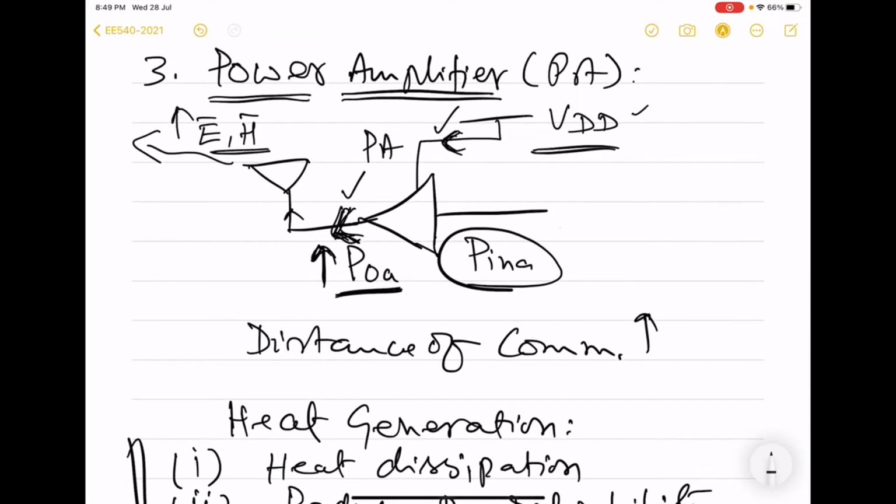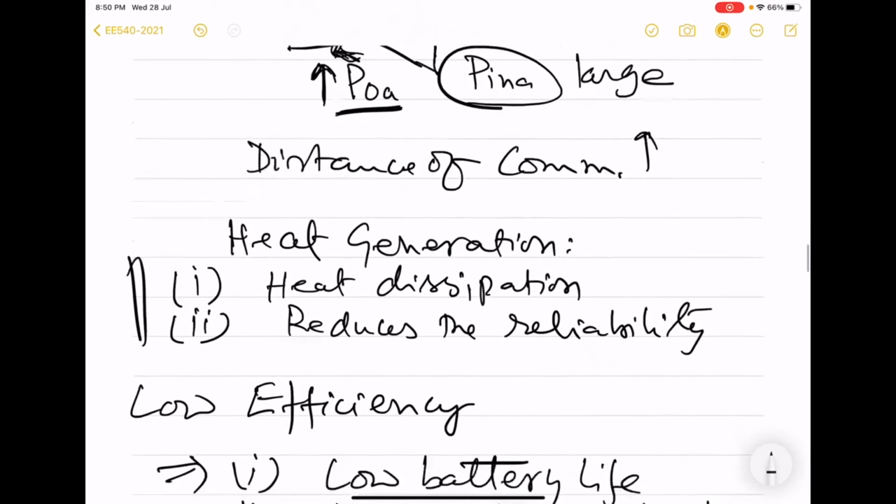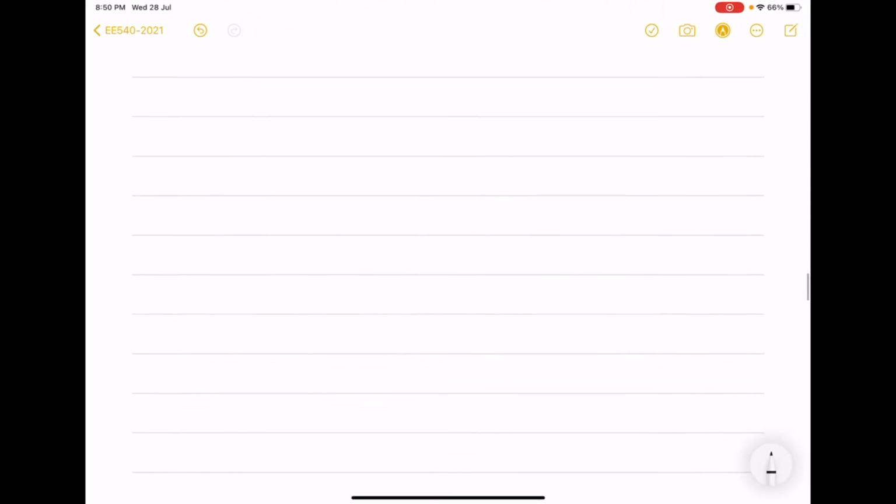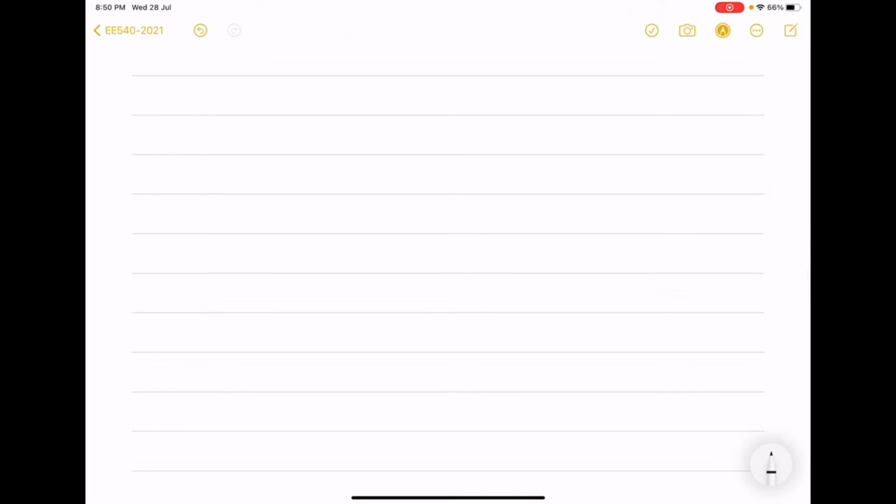Here, this input power that will be fed to amplifier will already be large because it is coming from microphone, and it can be amplified before being fed to the power amplifier. So here signal is going to be large. So we won't have to worry much about the noise added by this amplifier, which it will inevitably do. So that is why noise aspect of this amplifier is not much concern to us or to user or to designer also.